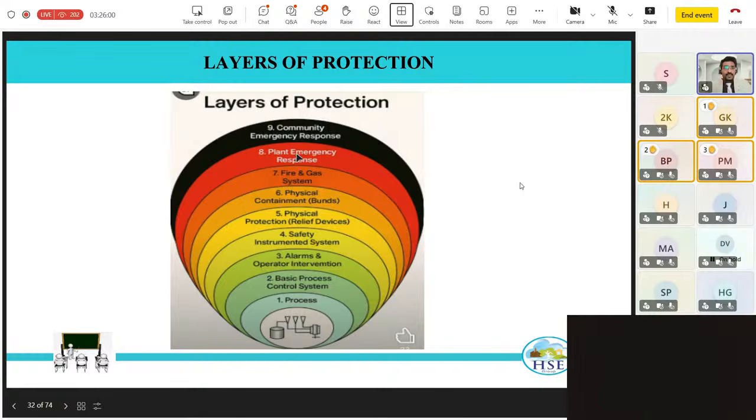In that case, basically, remember, you need to have that specific gas detector there. You cannot have a generic gas detector and claim that you will take credit. You need to have a specific gas detector which will alarm the community to evacuate, or which basically will ensure that your emergency response comes into play and they evacuate the community. There are several instances where the community could be on a small island and then it would become difficult to evacuate. So all those emergency responses are part of that safety planning, whereby the whole community can be evacuated.